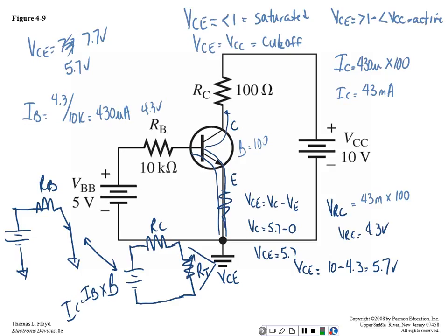No, you're thinking about a piece of wire. This is not a piece of wire. The temperature of metals go up, the resistance of metals go up. But here we're dealing with a current that's controlled by majority carriers. And what happens is when you heat electrons up, they become more active, right? You understand? Which means they release more majority carriers, which means the beta goes up. So in a transistor, it's not a piece of wire. Now metals, if you heat metals up, what happens to their resistance? Their resistance goes up. But this is not a conductor.